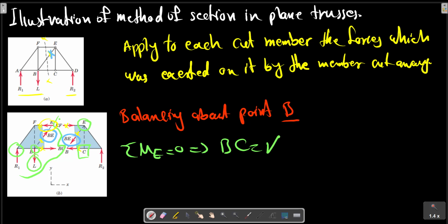A casual glance at the truss should lead to the same conclusion when it is realized that the lower horizontal member will stretch under the tension caused by bending. The equation of moments about joint B eliminates three forces from the relation, and EF can be determined directly.